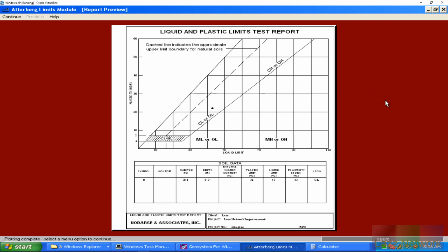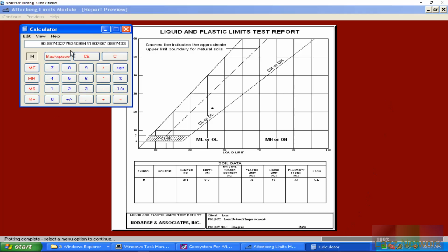soils, that's usually soils that are, and don't hold me to this because everybody's a bit different when it comes to organic contents, organic-y soils is like 25% and greater. If it's over 50%, you're almost sort of hitting the peat territory, but really you could just have highly organic-y soils. What really makes it peat is greater than 75% for your organic content. That's your guaranteed. Yeah, you got a messy situation on your hands there.